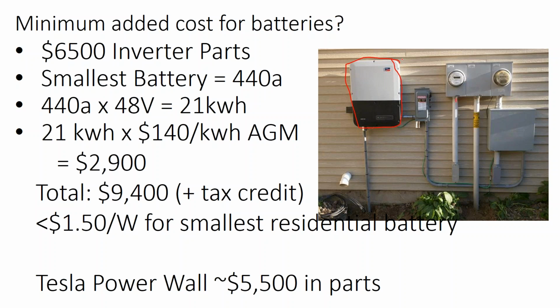What I don't like about SolarEdge is that because you're putting a box behind every module on the rooftop, that box becomes a failure point. My philosophy is to get rid of as many failure points on the roof as you can. So even though the SolarEdge system is a little bit more battery capable than SMA out of the box, to prepare this site we were fine just going with SMA and then adding a battery inverter down the line.